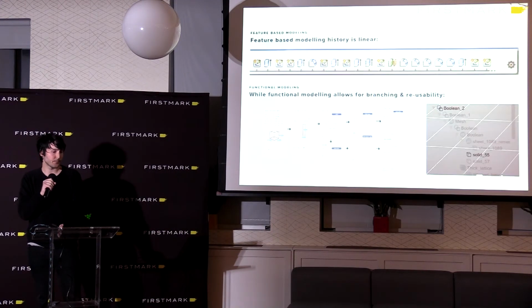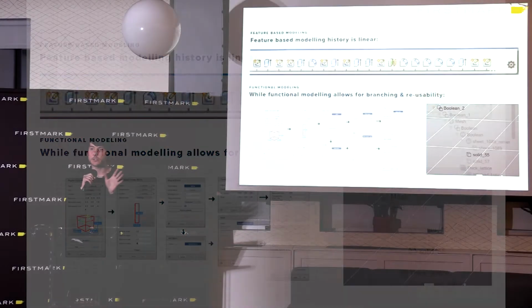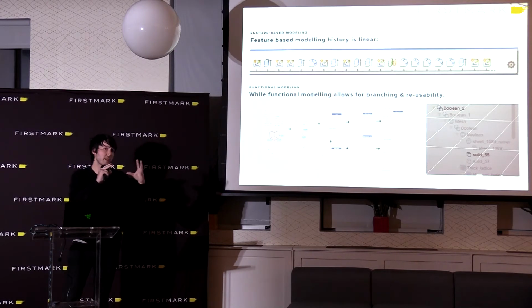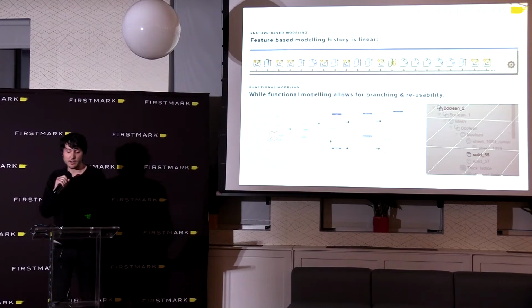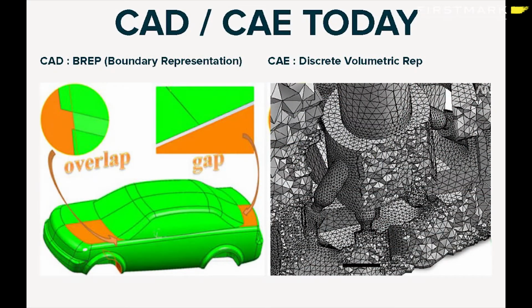And so then again on the workflow, when you look at traditional CAD, it's a very linear process. It's one step after another. You do a sketch in 2D, extrude, offset, extrude, and you tie these steps together. And so again, to create that shareable workflow, we're breaking down the design process into a graph, so that each node in the graph can represent a single operation to create these shareable components.